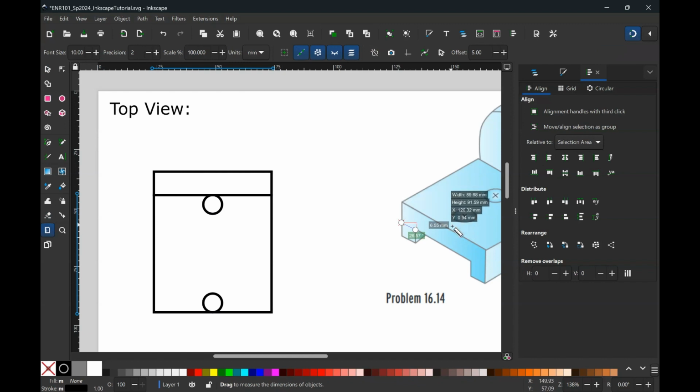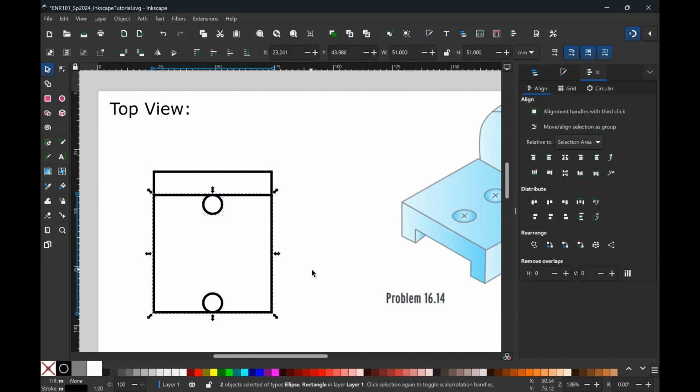Doing a quick measurement of where these holes are relative, I can see that they're offset from their edge by less than a tenth of the distance. So I'm going to offset this. Now that they're aligned with the bottom, I can physically change what their dimension might be. So we're going to bump this up by 5 millimeters, which looks okay. It's probably a little less than that. So let's say we'll go by a good 10 millimeters on one side.